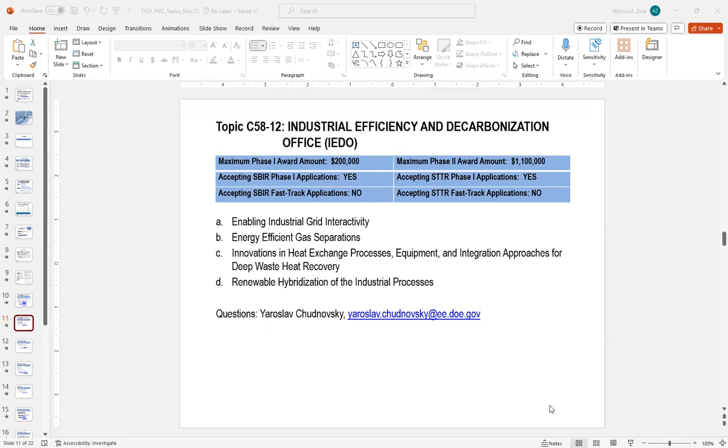So if it were a filter, an HVAC filter that took water out of air, that would be impactful because then you don't cool down that water, and there's a lot of energy that goes into condensing water out of air in HVAC systems that you would successfully avoid if you could separate out the water molecules from the air molecules, and a whole range of impacts would fall out from that kind of high precision separation, because all of a sudden you would have super dry gas that could be applied in paint drying, for instance, an energy intensive process.